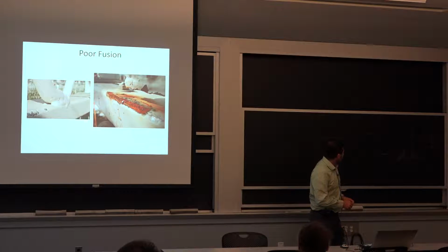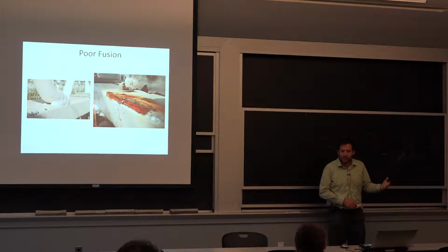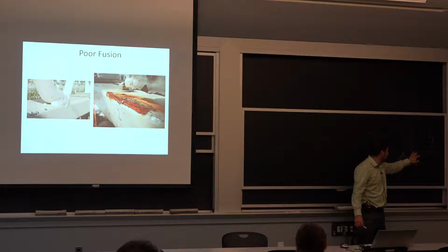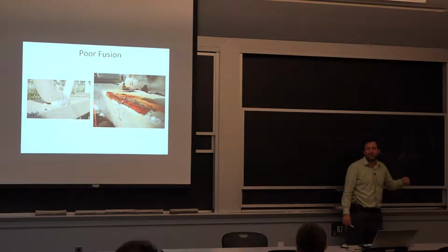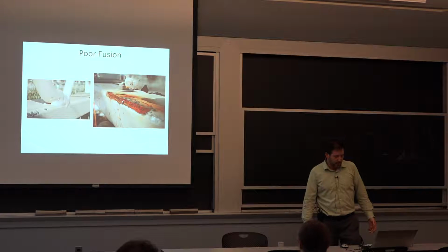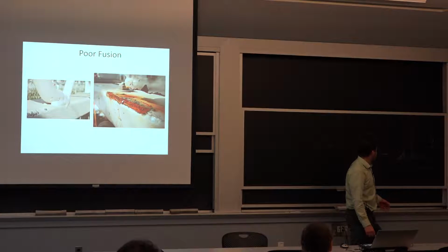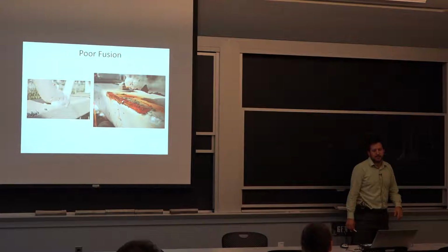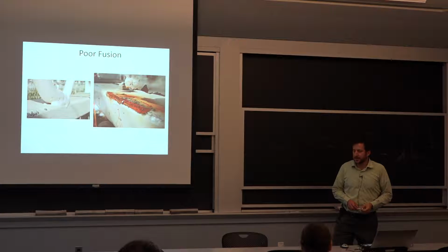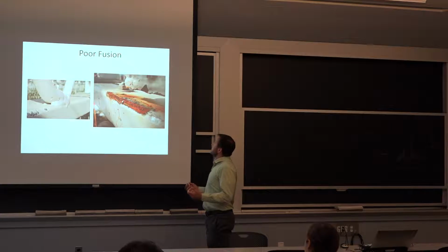There are criteria in terms of the convexity of the weld that I may be able to use sometimes. So if it's really rounded this way, you also have too convex of a weld. So there is a requirement for that. But in terms of just knowing that you may have a risk that you did not fuse your base metal, it's a little bit left to the inspector. Now, after the fact, it's very easy to do.